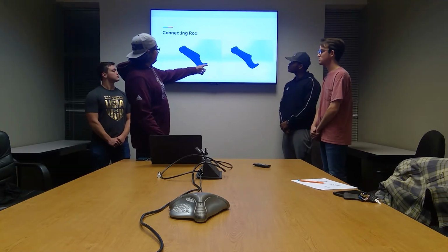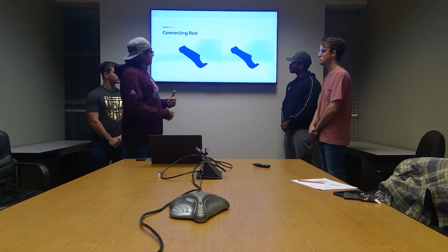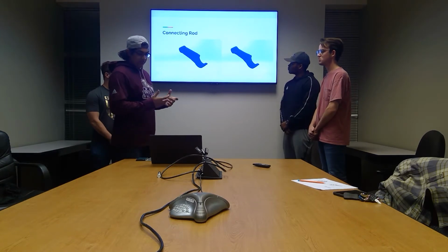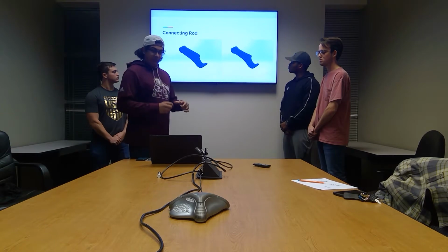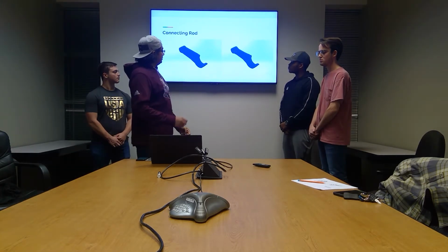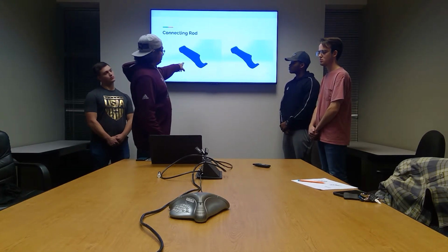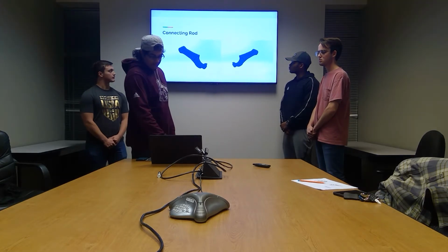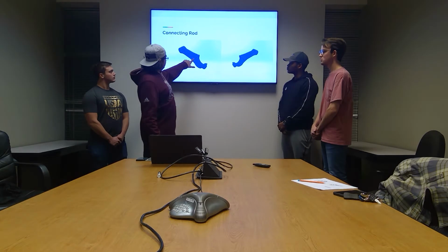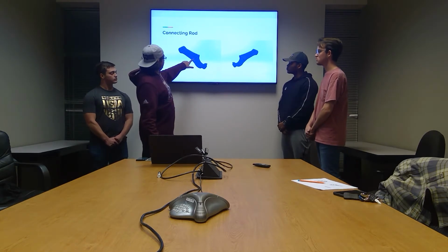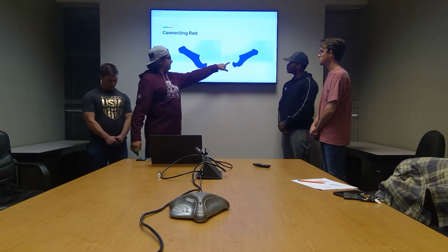On the right side, we have the inside cuts to the little I-beam, basically, between the two circles. And I just created that with 3 different widths, and then just cut it from the giant block that I had started with. After that, I added a few details with the little outer face right here, this little notch, and that's on both sides, as seen over there.